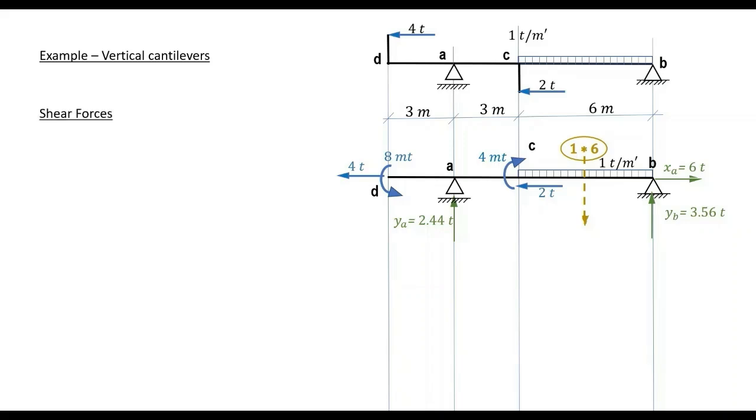To plot our shear force diagram, we search for all forces perpendicular to the center line of the beam, as we explained previously. If we start from the left side, D, we will head up on the diagram with all upward forces and vice versa.